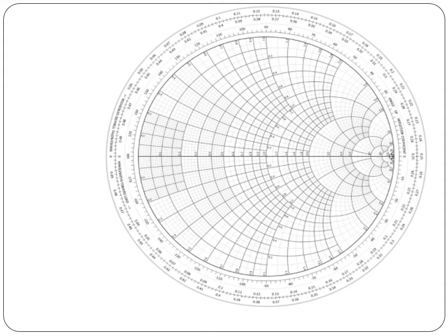Normalized ZL is 1.9 plus j1.1, which is in the form R plus jX. In the Smith chart, 1.0 is always the center of the chart, name it as O. So here I have to mark the R equal to 1.9 resistance circle.